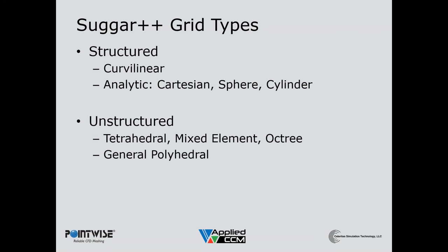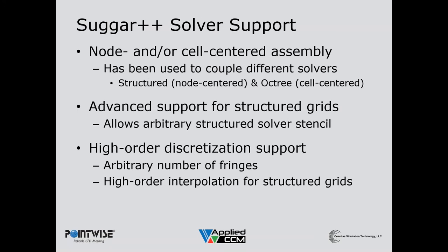Suggar++ supports basically all the grid types that you need: structured curvilinear and analytic grids, the usual unstructured grid topologies, including general polyhedral grids. Suggar++ supports node and/or cell-centered assemblies and has even been used to couple different flow solvers. In one example, a structured node-centered solver was coupled to a cell-centered unstructured octree-based solver through the use of the Suggar++ computed overset domain connectivity information.